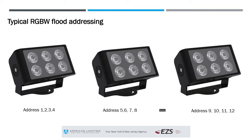The next one would start at 5 and it would consume 5, 6, 7, 8. And then the third one, 9, 10, 11, 12. So in this application, addresses 1, 5, and 9 will all control red. 2, 6, and 10 will all control green. 3, 7, and 11 blue, and then 4, 8, and 12 would control the white channels.